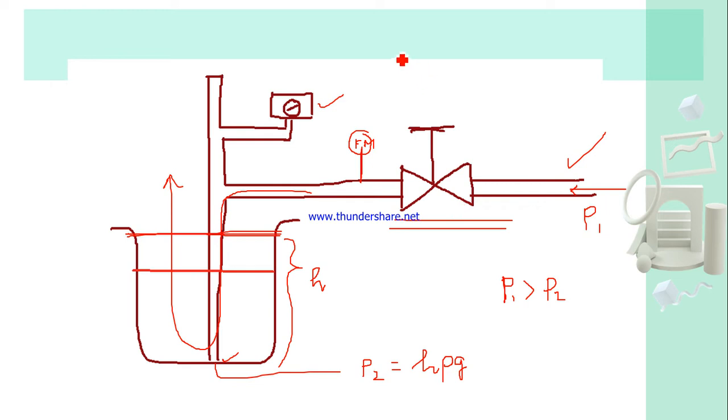and through that, you know that the differential pressure is equal to some non-dimensional flow coefficient or flow loss. You can say this is a loss, sigma, into rho V square by 2, as per Bernoulli's law. So now your V square is equal to 2 by sigma into dP by rho.